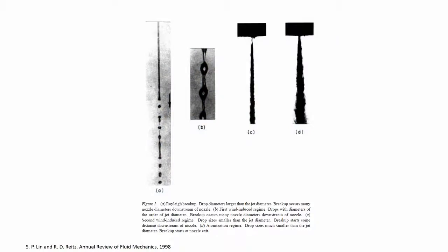So, here is another slide before we go into the analysis. Here is another slide that shows you the different modes of how these small droplets can be formed. So, this A is essentially this Rayleigh breakup, where you see that this laminar smooth jet is coming down, where there is no disturbance, and then after some time small perturbations get amplified into this, and then this disturbance forms, and then you see the formation of these droplets which sometimes merge, etc.